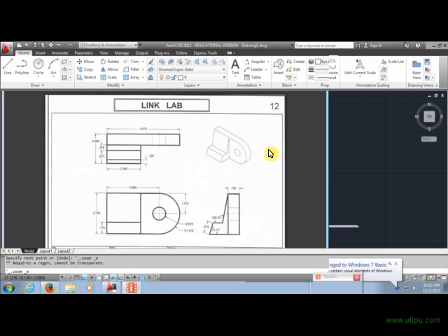Now, what I need to do at this point is to draw a line back that shows the width of the object. So I get back into line, I click on this corner, and obviously you'll see I can't draw in that direction, so I need to hit my F5 until I get to the point where it will let me draw in that direction because it's the isoplane for top. And I need to do it the width of that section, which is 0.75. And then I want to do the same thing on the bottom.